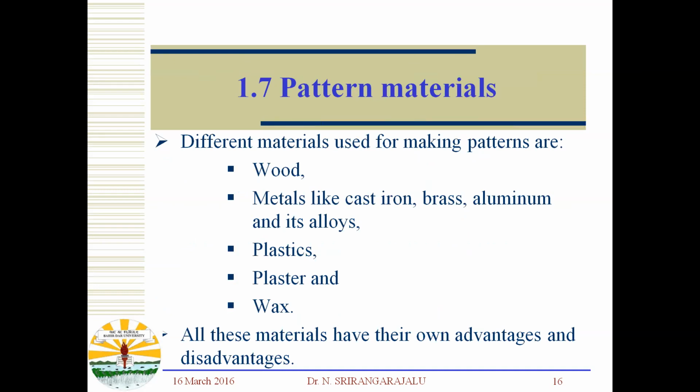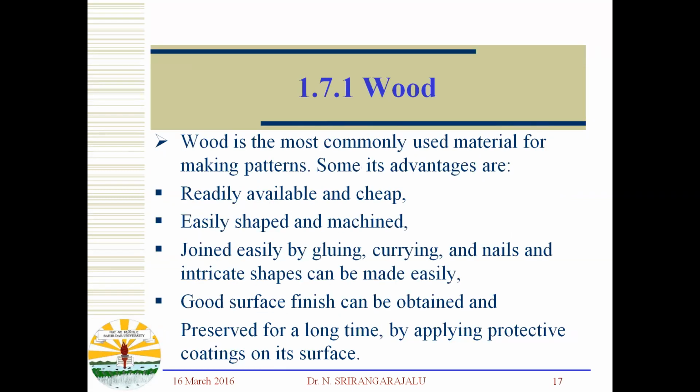So different materials used for making patterns are wood, metals like cast iron, brass, aluminum and its alloys, plastics, plaster and wax. All these materials have their own advantages and disadvantages. So first we will discuss wood. Wood is the most commonly used material for making patterns.